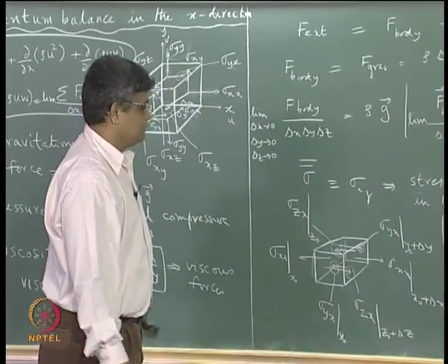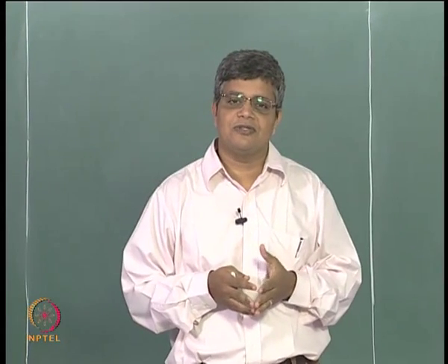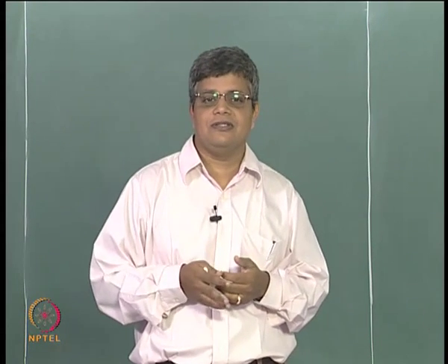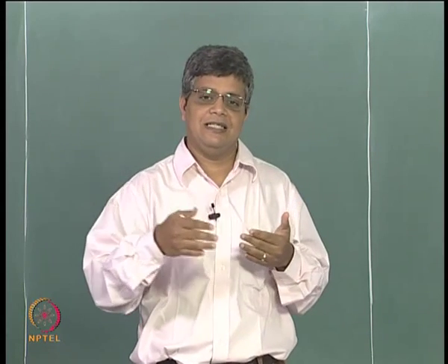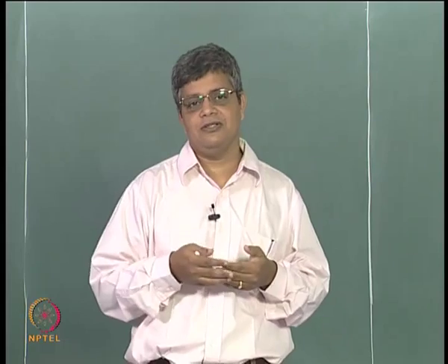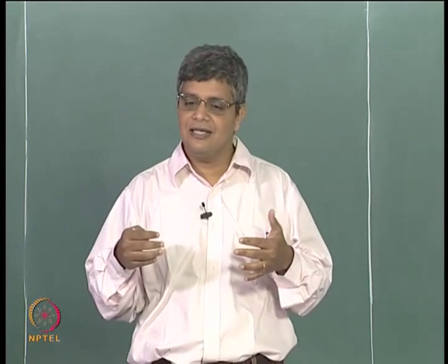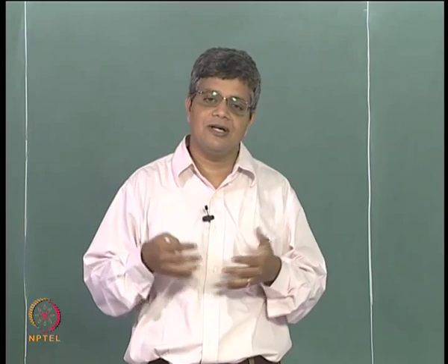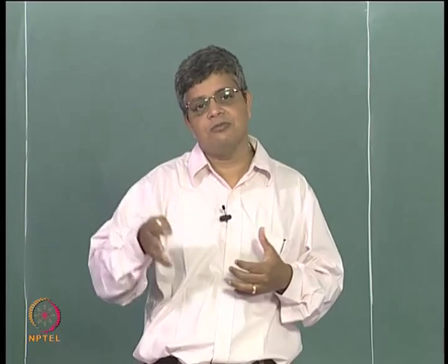So that we will do now. It is now making a generalization of Newton's law of viscosity, which expresses a relation that the shear stress is mu times du by dy, or shear stress is proportional to the strain rate. Okay, in the process of generalization we also want to understand better what exactly we mean by strain rate and what exactly we are modeling in this.